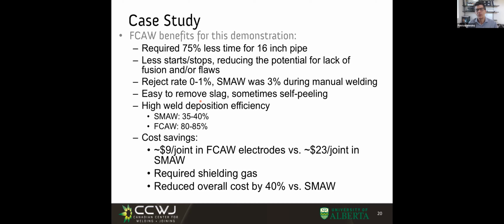But pretty much every time you do some sort of a cost analysis, comparing stick welding with flux core, if you have the equipment, if you have people trained to do flux core, very often, especially if you have some amount of production, flux core is going to win. The advantages of stick welding, that is flexibility, are becoming niche advantages, and liabilities when we talk about production, especially production in shops. All right. So I think this was it about the naming of welding consumables.